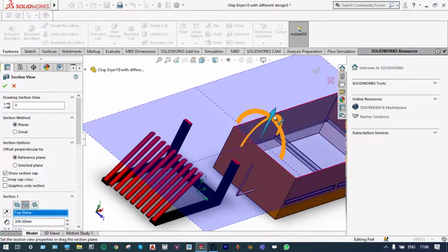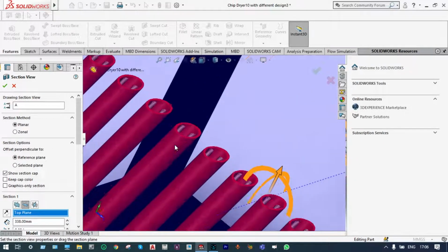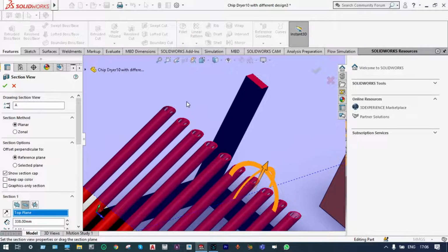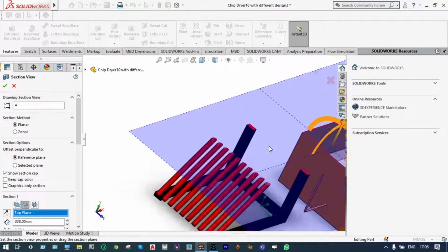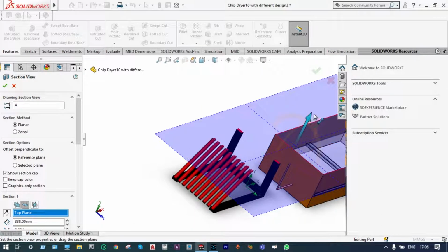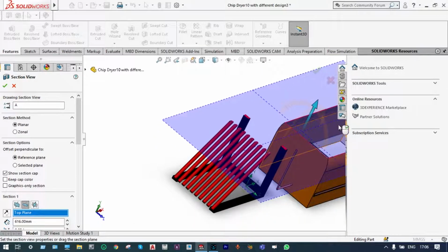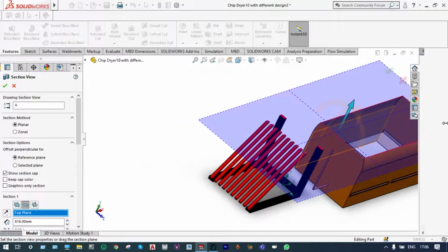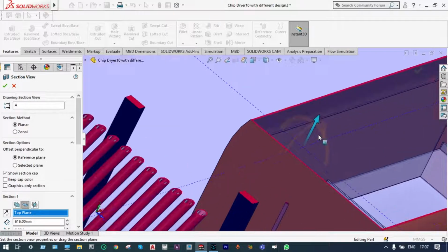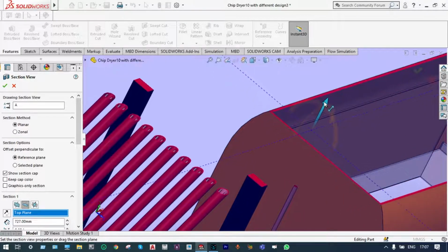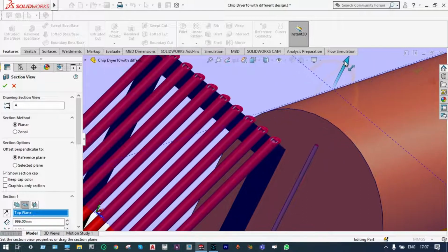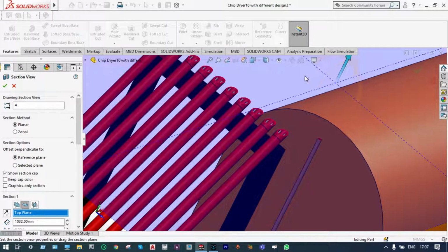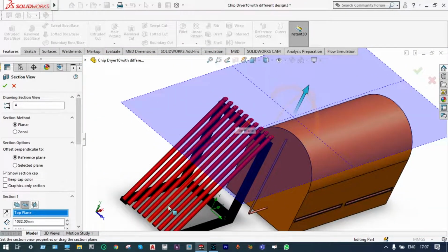You can see the pipes. In this way, you can see inside these pipes we have copper tubes. A U-shaped copper tube is provided inside these evacuated pipes. A very small amount of fluid will be there at a pressure of 0.4 bar. Okay, again we can drag it in a better way. You can see this construction. At this location, the copper tube is closed. That means it will be evacuated from the bottom up to this position.